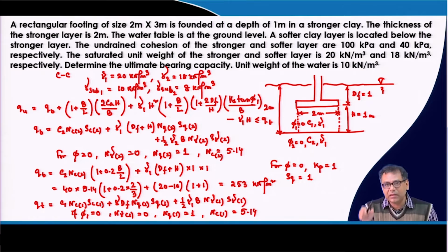So, the total soil along with the foundation moves, and the stresses act on the bottom layer with a width equal to the width of the foundation. That is why we always take B, whether it is the top layer or the bottom layer. That is why during the QB calculation also we have taken B, and H as mentioned.